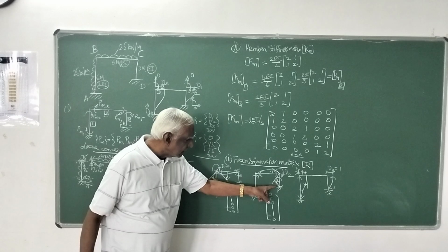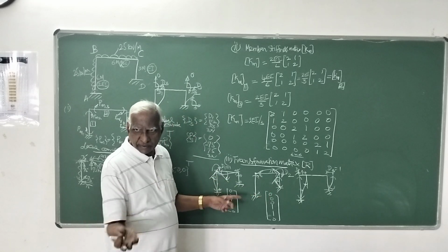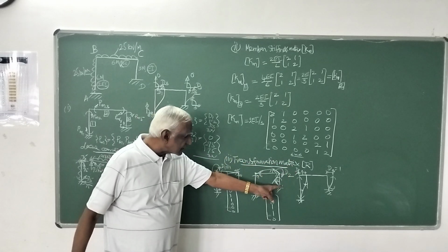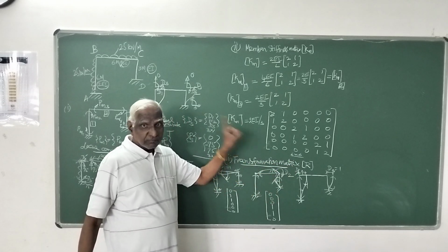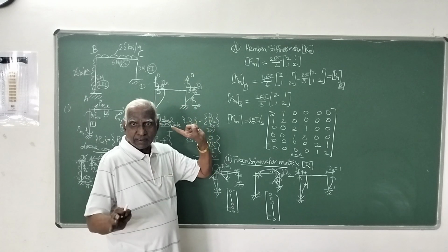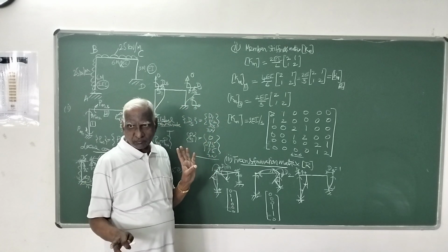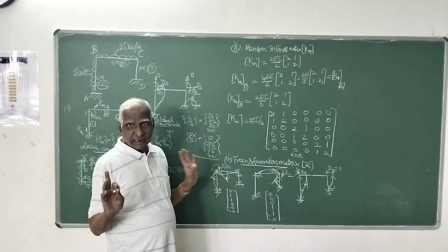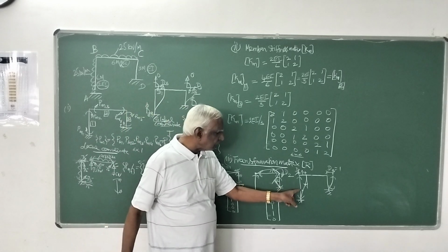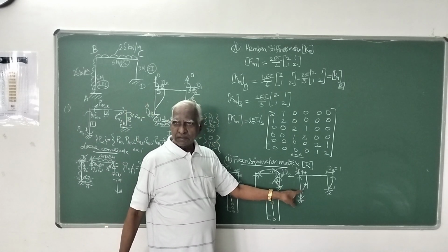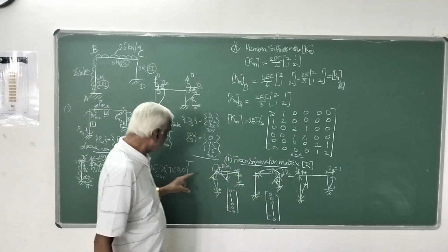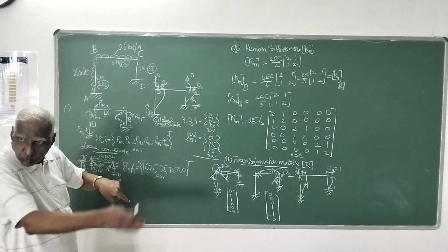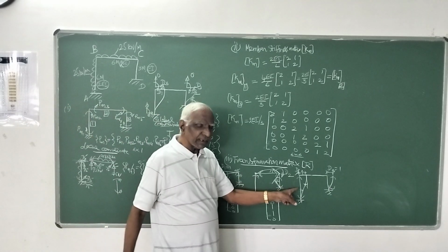So here, sway displacement delta is taken as negative if it results in clockwise rotation, whereas force, that is moment, is positive if it is clockwise. Sway moment is opposite to that. That you have to remember. So here, what is this sway? This displacement, because we have to find displacement corresponding to PM, that is rotation. What is the rotation here?